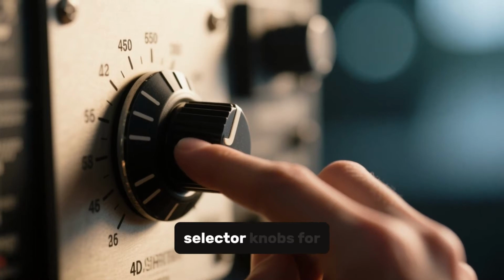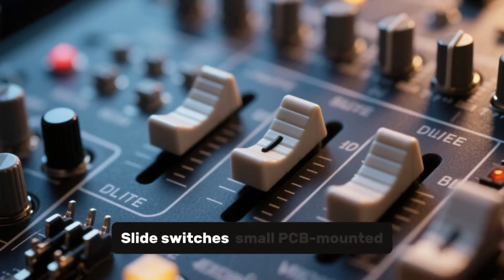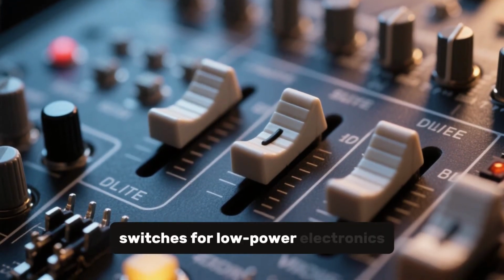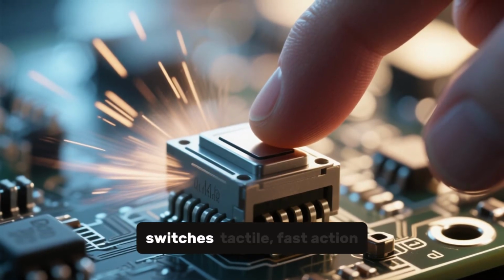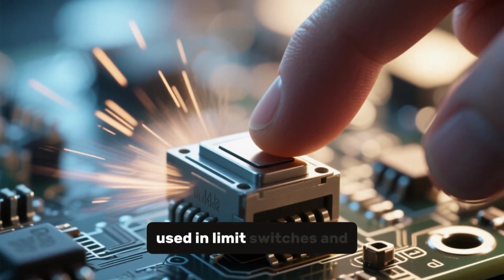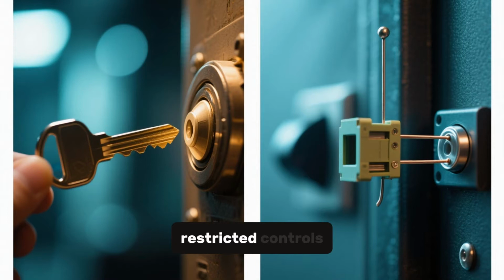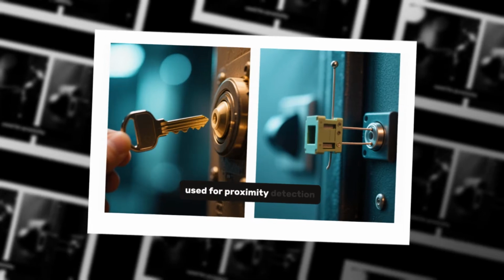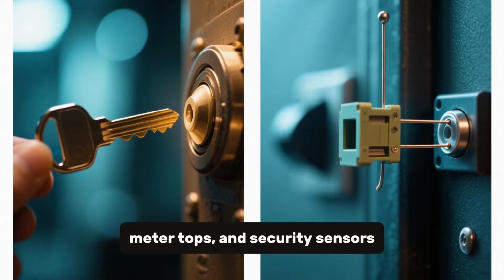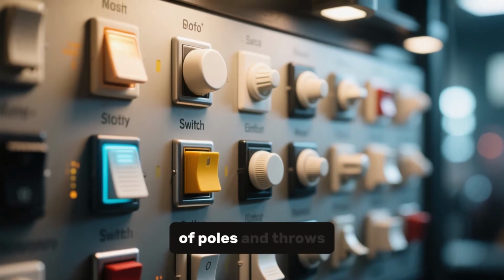Rotary switches, selector knobs for multi-position selection, e.g., range selector in instruments. Slide switches, small PCB-mounted switches for low-power electronics. DIP switches, dual in-line package switches used for hardware configuration. Microswitches/snap action switches, tactile, fast action, used in limit switches and appliances. Key switches, for secured switching, ignition, restricted controls. Reed switches, sealed glass with magnetic actuation, used for proximity detection, meter tops, and security sensors. Visual suggestions: show each type on screen with labels and a simple animation of poles and throws.